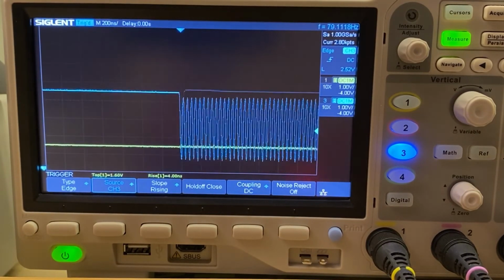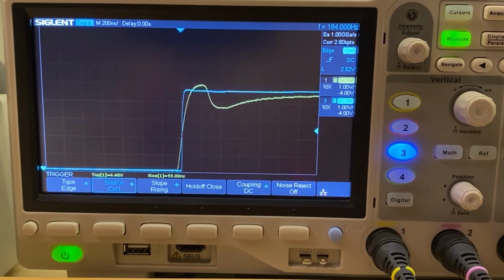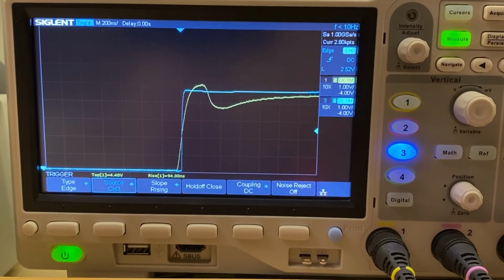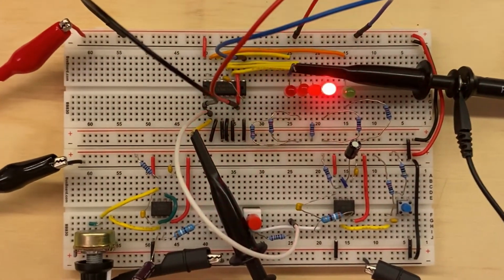And the moment I pull out the capacitor, then it's good, right? Now our clock rises up nice and fast, and so does the output. It's no longer confused. It's like, oh yeah, you're going up, I gotta go up too. And so that's the importance of the clock signal. It's very important. And you might ask, well, just don't put a capacitor on your clock signal. And of course that's correct. We would never do such a thing.